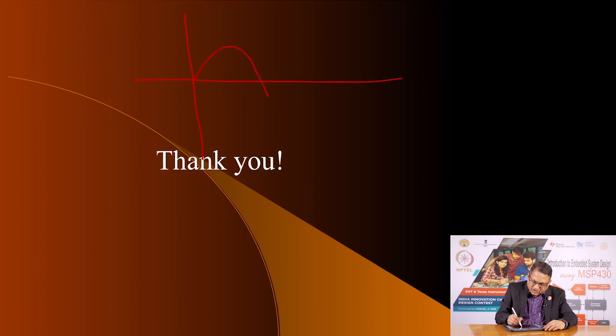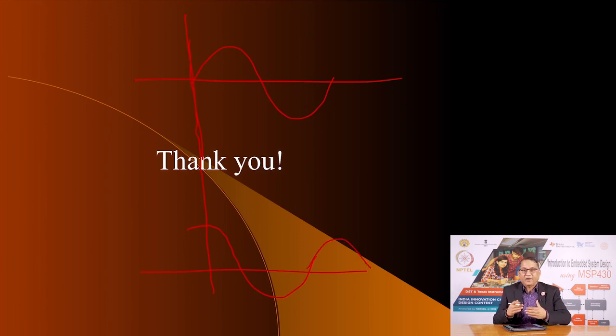So, let us say this is your sine wave and you wanted another waveform which is synchronized with this, but something like this. So, you can easily create two waveforms which are matched, locked to each other under the control of the microcontroller. You can easily do that using a PWM function.